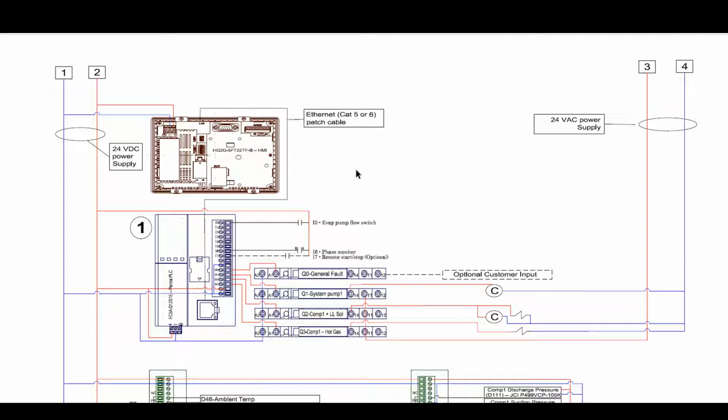In some cases, in some climates, just by use of a variable frequency drive for the condenser fan motor, we can circumvent the use of more expensive low ambient options, such as flooded condenser, which makes the net price to the customer quite a bit more competitive. So anyway, that's pretty much it for this SmartDrop item. This is how a variable fan speed control operates using a VFD drive, and I hope this information has been helpful to you.